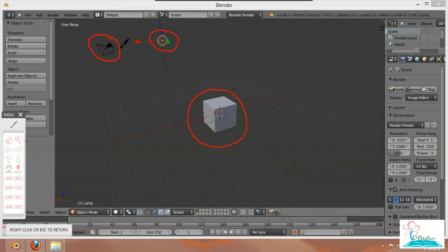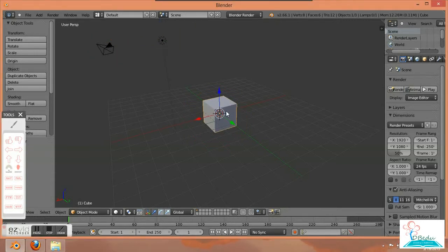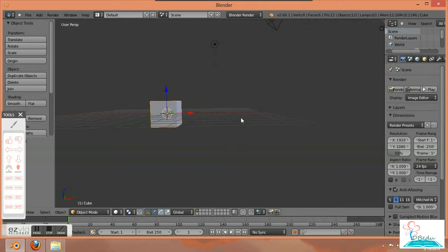Now these are all the three things we will not use in this, but we will use only and only the camera. Okay, and we will add some text. If you want to move it horizontally, then press Ctrl and along with Ctrl scroll your mouse wheel button. And if you want to move it vertically, then press Shift instead of Ctrl and do the same as you did previously.